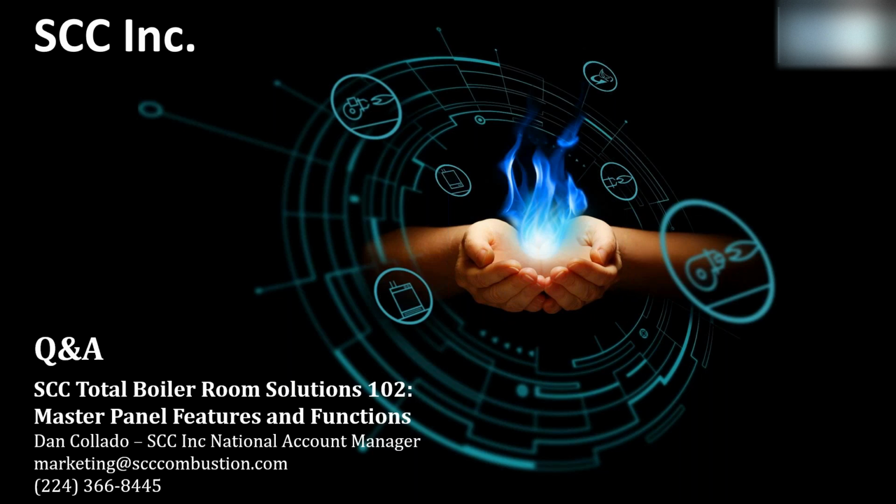Okay, again, a very common question. I'm not surprised it was asked again, but the answer to that is basically no. Big picture, the master panel, our local touchscreens and PLCs are digital communication devices, and there's a lot more programming than you realize that goes into making these products. So for applications with third-party controls that require lead lag, auto rotation, hot standby, low temperature, low fire hold, the minimum requirement that we need at each burner boiler is an RWF55.